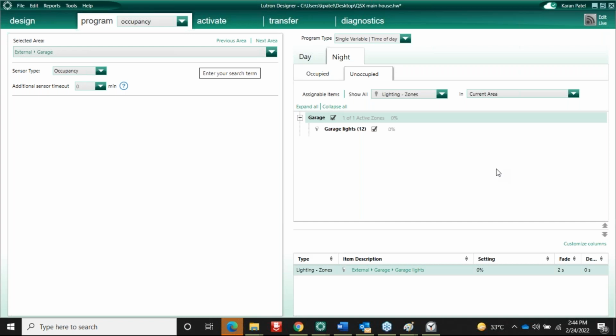What is the kilowatt rating you suggest for a UPS for a particular system? For DALI, we consider the module as about 50 watt standby power. Then our processor will take maybe 50 watts. We have the list of the control power, like which module consumes what. Based on that, if you want to give only control power, then maybe 2 kilowatt of UPS is more than enough, only to give the control power.